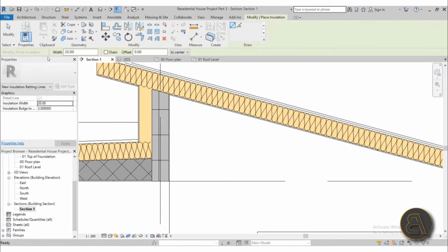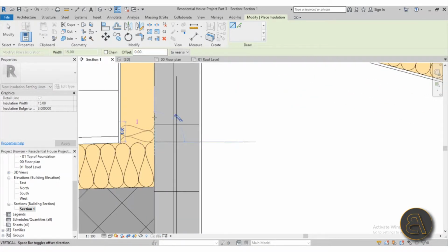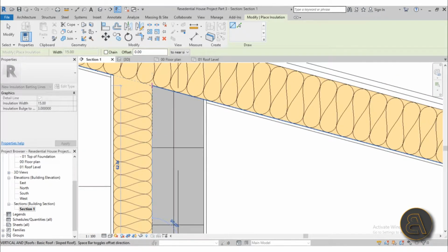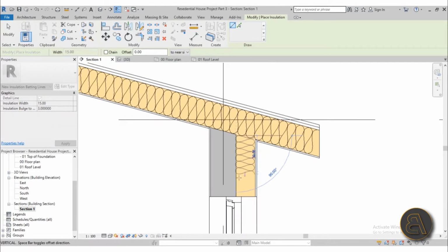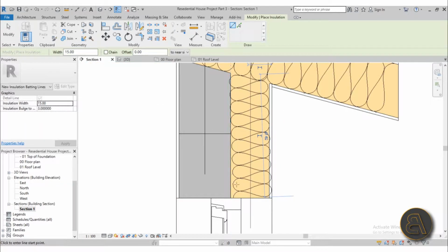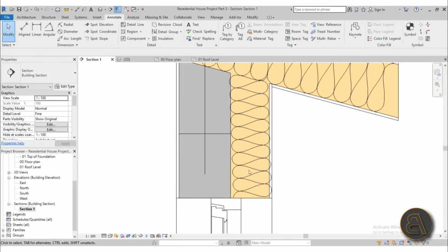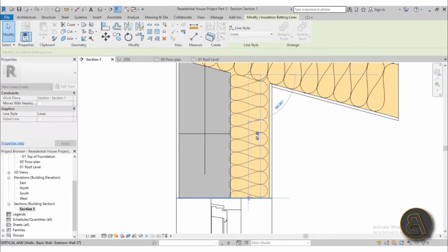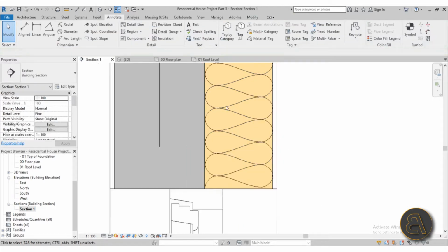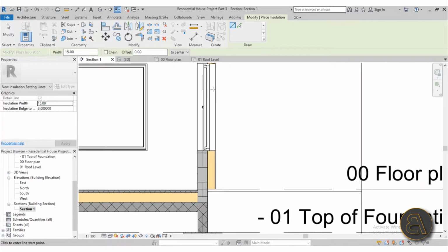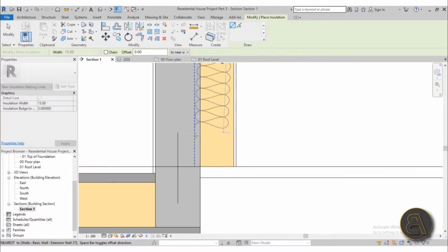Okay, so now to complete the walls, let's go with 15 near side, and let's go from, I don't know, from here. So you kind of have to play around to fit your insulation the best way possible. Let's go from here down to the window. Oops, it went off to the side, so you can select it and try to recenter it a bit using the arrow keys. Okay, let's go back into insulation, 15 near side, and let's do this one.